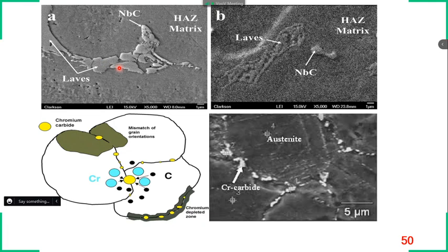It consists of a lot of niobium carbide and a lot of interstitial strengthening elements, which is highly detrimental from the fatigue perspective and also from the tensile strength perspective. We cannot avoid this kind of Laves phase, especially in Inconel 625. Maybe we can reduce the size, but we cannot avoid it.